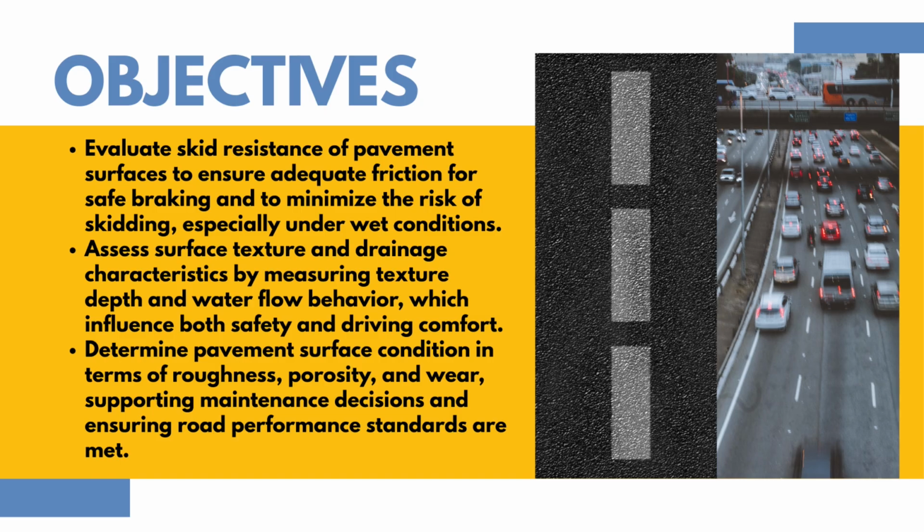These tests aim to evaluate skid resistance for safe braking, assess surface texture and drainage to ensure grip and comfort, and determine pavement condition like roughness and wear to support maintenance planning and meet safety standards.